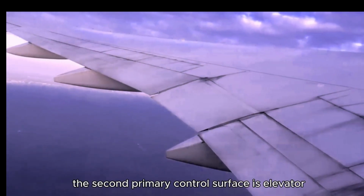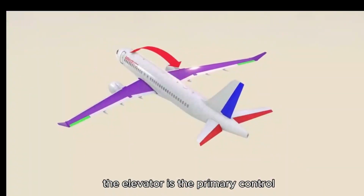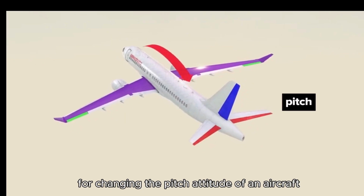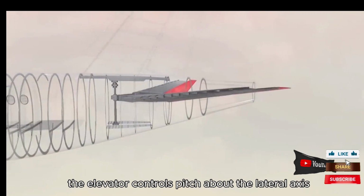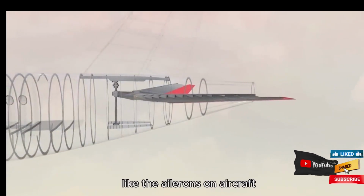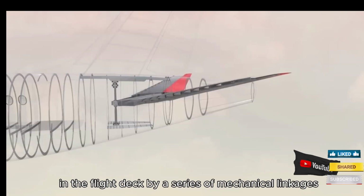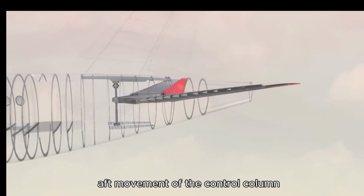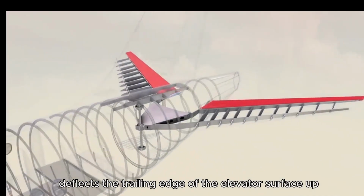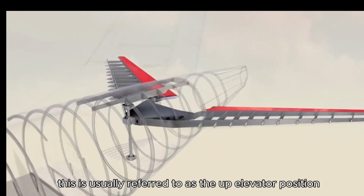The second primary control surface is the elevator. The elevator is the primary control for changing the pitch attitude of an aircraft. The elevator controls pitch about the lateral axis. Like the ailerons on aircraft, the elevator is connected to the control column in the flight deck by a series of mechanical linkages. Aft movement of the control column deflects the trailing edge of the elevator surface up. This is usually referred to as the up elevator position.